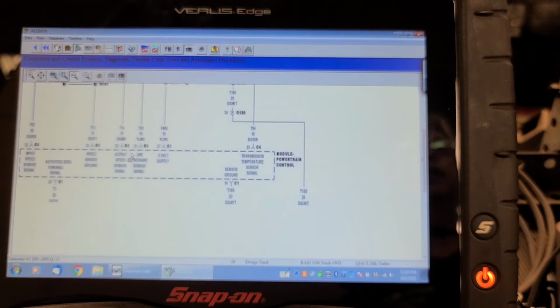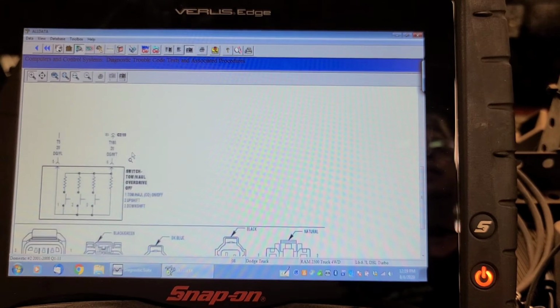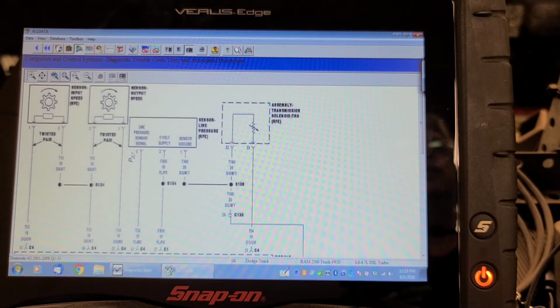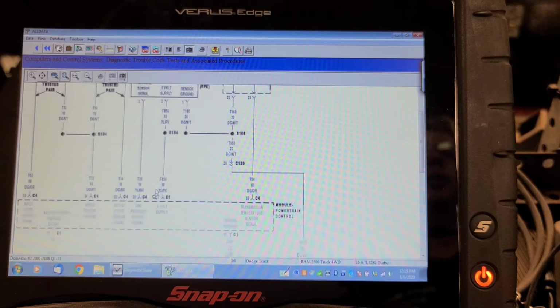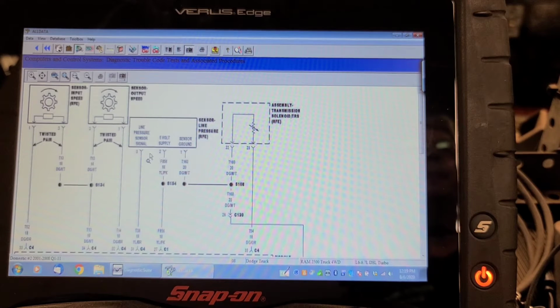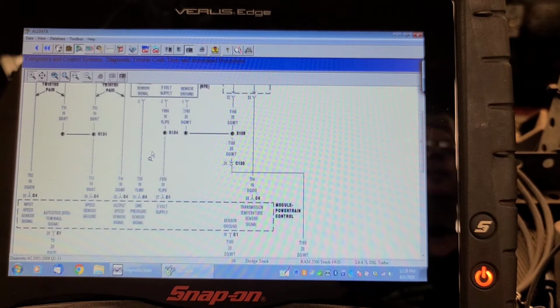So here is, that's the Hall switch. Where's the pressure? Oh, here we go. I think these are common for the pressure sensors to fail. This transmission has been replaced a couple of times. So if it's seeing more than 5 volts on this, now that could be an open circuit, depends whether this has a pull-up resistor or not in it. I think we're going to check continuity of the wires from the PCM to the transmission. Let me look at this for a minute.